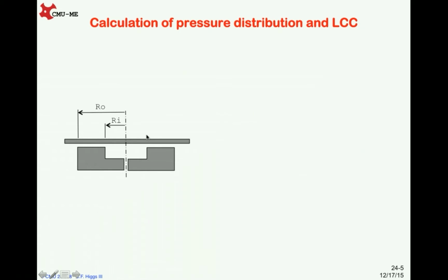Here I'm going to show you how to calculate the pressure distribution and load carrying capacity for a hydrostatic bearing, which is also called an externally pressurized bearing. The reason we call it an externally pressurized bearing is that in the region shown here, which is called the recess, the pressure is provided by a pump, and the pressure in this region is kept constant, which is PR. The pressure outside this contact region is called PA.